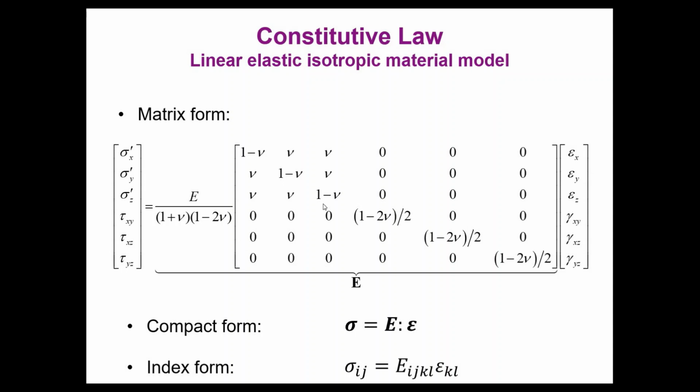When we say that the model is isotropic, this means that the mechanical behavior of this material, this mathematical material that is defined mathematically, is the same in every single direction of the three-dimensional space. This produces a reduction in the number of elastic parameters we need to define the model mathematically. And when the model is isotropic, the only 2 elastic parameters we need to define this model are the Young modulus E and the Poisson ratio nu. So as you see,